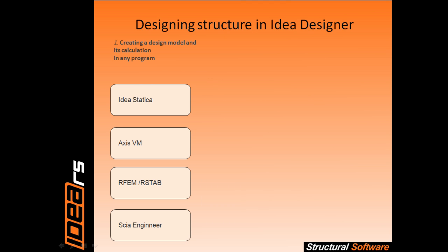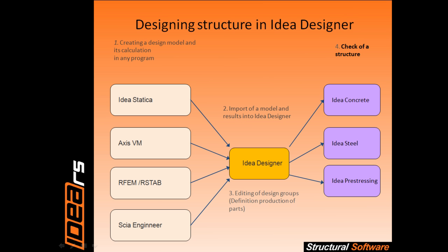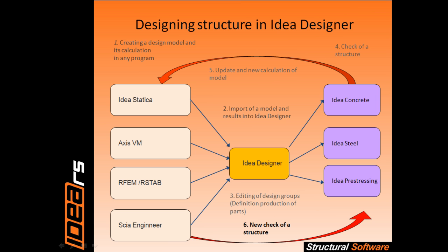Calculation of the structure is done in desired structural analysis program. Then the whole model including the results is imported to IDEA Designer. The structure is divided into design groups and these are designed using modules IDEA Concrete, Steel and Pre-stressing. After modifying cross-sections, the structure can be recalculated using original finite element analysis program and then rechecked for internal forces.